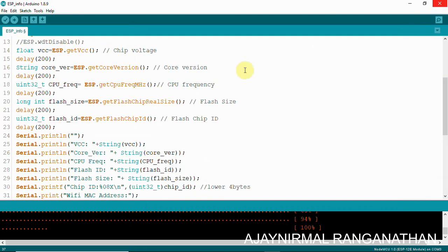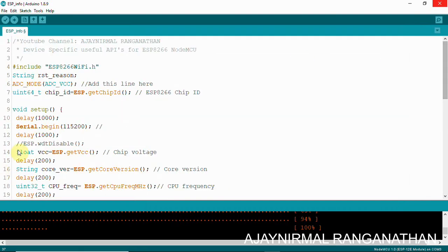And then we will discuss the watchdog timer. I told you that we'll be discussing this watchdog disable, which is actually a software watchdog disable. The watchdog reset I discussed before happens when you send the R command from the terminal to the device, and it will show you a WDT reset with reset cause number 4.